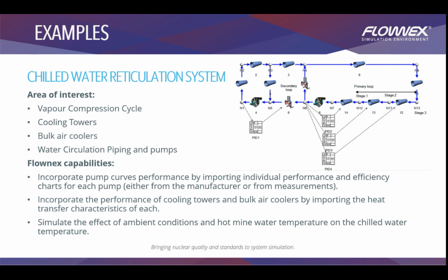So you can incorporate pump curve performance by importing individual performance and efficiency charts for each pump. These charts we can get from the OEM, and you can load them in Flownex as well. You're not limited to the charts that are already in Flownex, so you'll be able to load your own performance and efficiency charts for each pump in Flownex in order to model your system as accurately as possible and obtain efficient results as well.